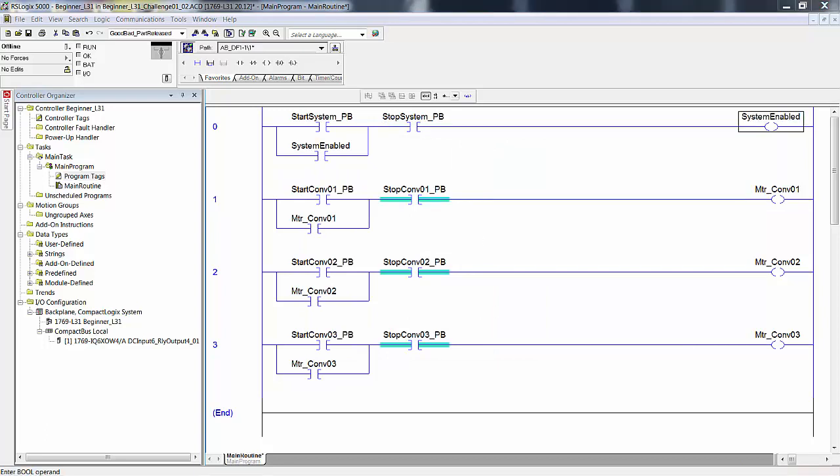Another thing with your new rung, this gives you a bit that the operator can energize and de-energize as an indication to the controller that the conveyors are enabled to run or shut down and not enabled to start. But what do we do with this bit and the other three rungs to effect or cause that functionality?